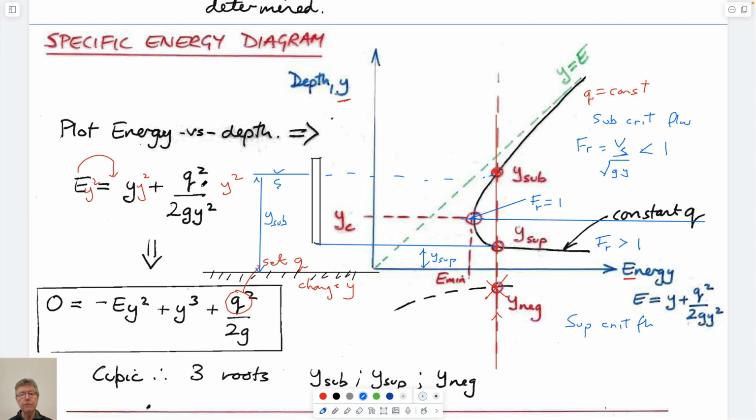So this is the same flow velocity, same volumetric flow per unit width of the channel upstream as it is downstream, because if you take a section across the upstream and downstream, continuity requires that that's the case. It has the same flow. It has the same energy because we're not losing any energy in the system because we're satisfying Bernoulli. We've got a horizontal base, which means that S0 equals 0. We have no head loss in the system. So HL equals 0. So what we called SF, I think, right, is equal to 0.